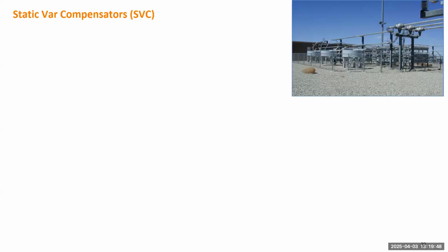It's just a combination of many reactors or capacitors. You can decide to adjust the regulator or switch in or switch out capacitors to give you the desired var. Static just means there's no rotating part, but it can behave similar to a synchronous condenser.